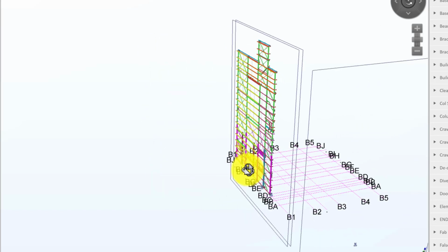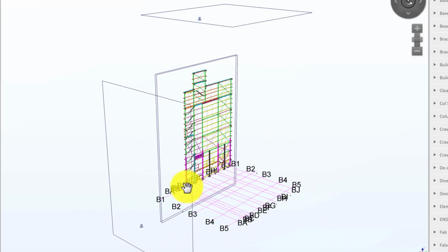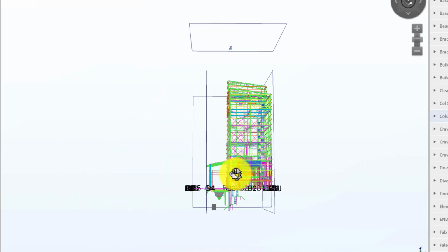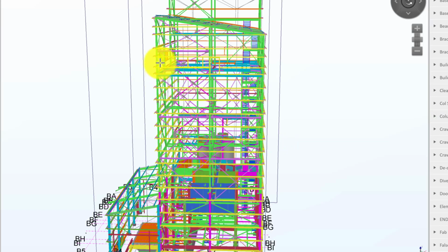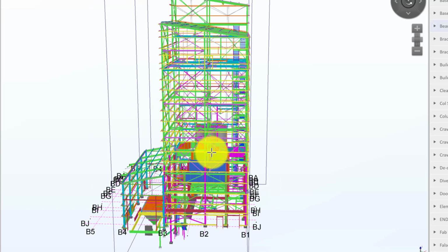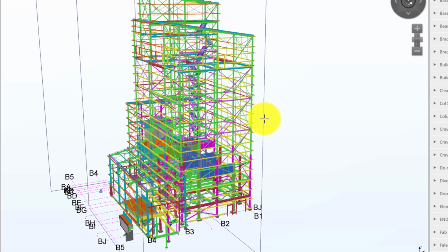Now, coming back to this, here you can see that we had two specific main brace bays carrying the bulk of the load. If I take an end view, it would be on the left-hand side here and on the right-hand side. All the loads applied to all the faces would be spread across to those braced bays through floor bracing or various other means, and then we would design each of those braced bays.